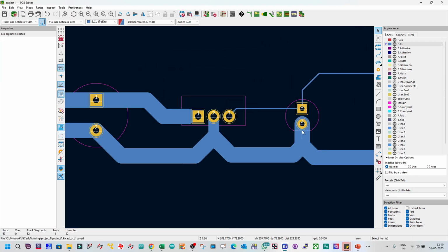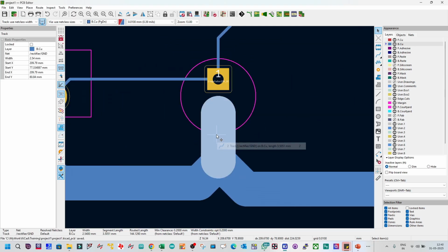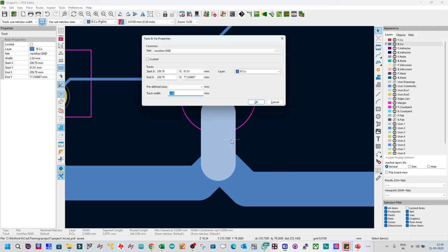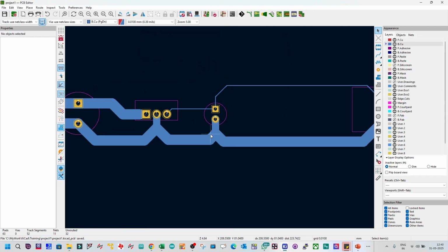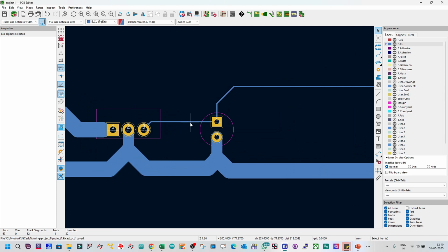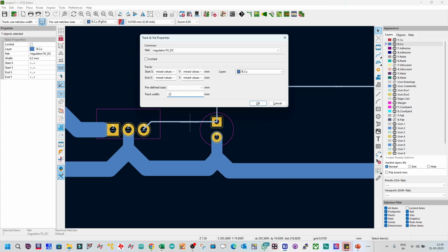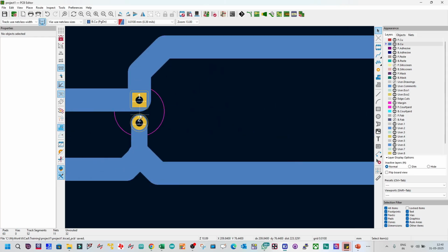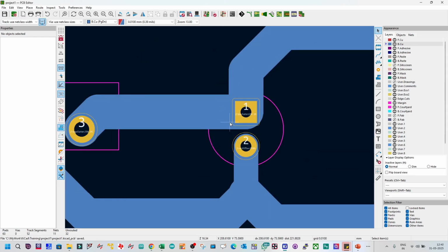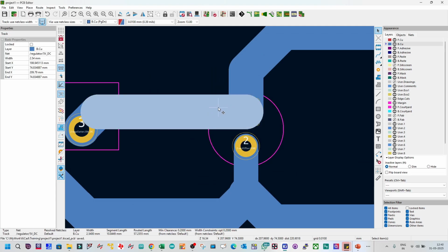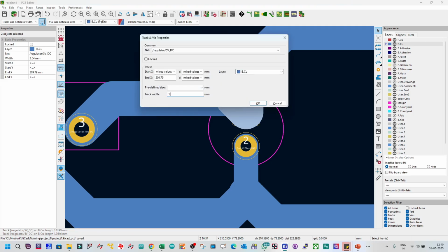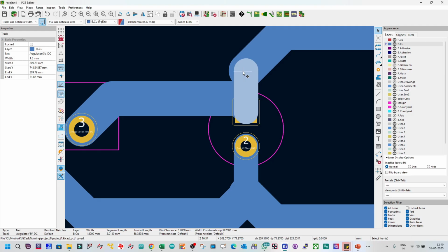So let us complete whatever we have done so far, and then I will cover the next part. Select the net fully, then hit E and make it 2.54. This connector is good, there is good spacing maintained here. This capacitor's clearance is getting into a problem. Maybe we can make small tweaks to this so that the problem is gone.